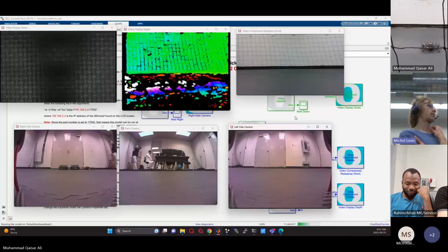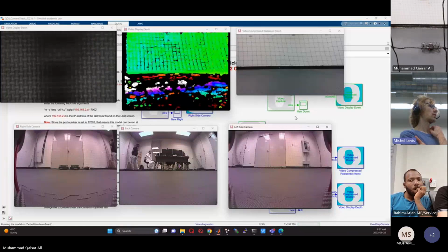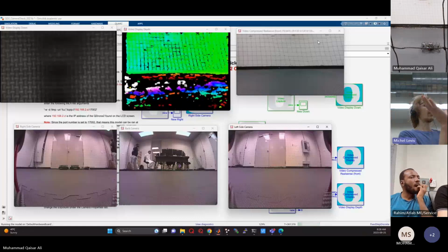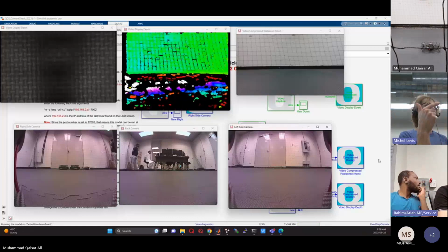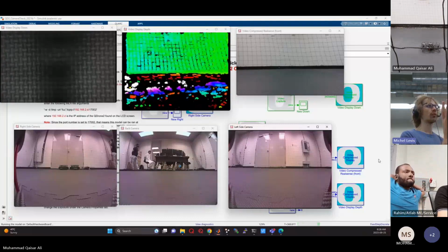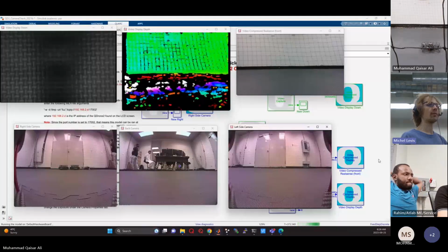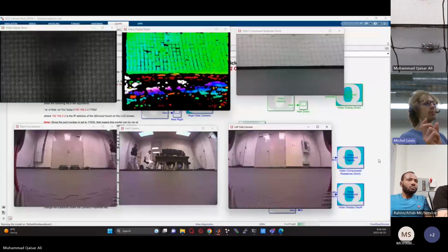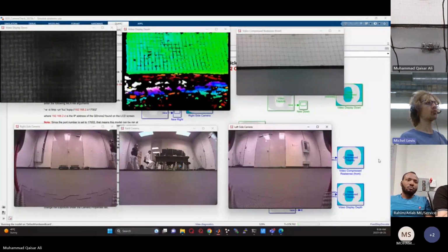You're not getting a full 360 like the QCar. In this case, you're not getting a full 360, but I think it's probably enough for detecting most objects, right? Because each one is plus or minus 80 for the CSI cameras on the right and left, and the back one, and the front one is 42 total, so plus or minus 22.5 or whatever. So the front camera, you might have a little blind spot there, but not very much.